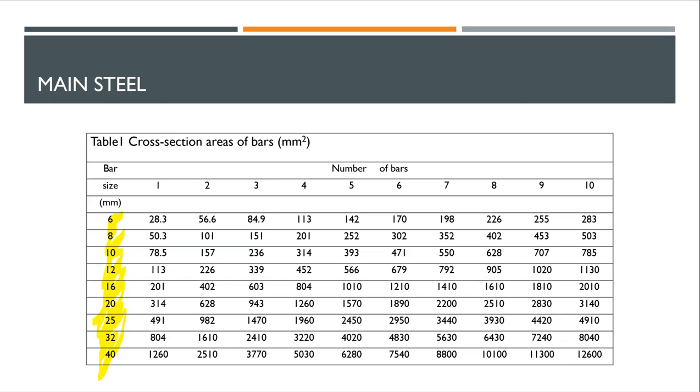And like in example number 1, if you still remember, those who attended the class, I said that for footing we worry if the bars are too far apart, we don't worry if the bars are too close, because the bar area is big, long and wide. So we don't worry about not having enough gap for concrete to fill inside. No, we don't worry about that.